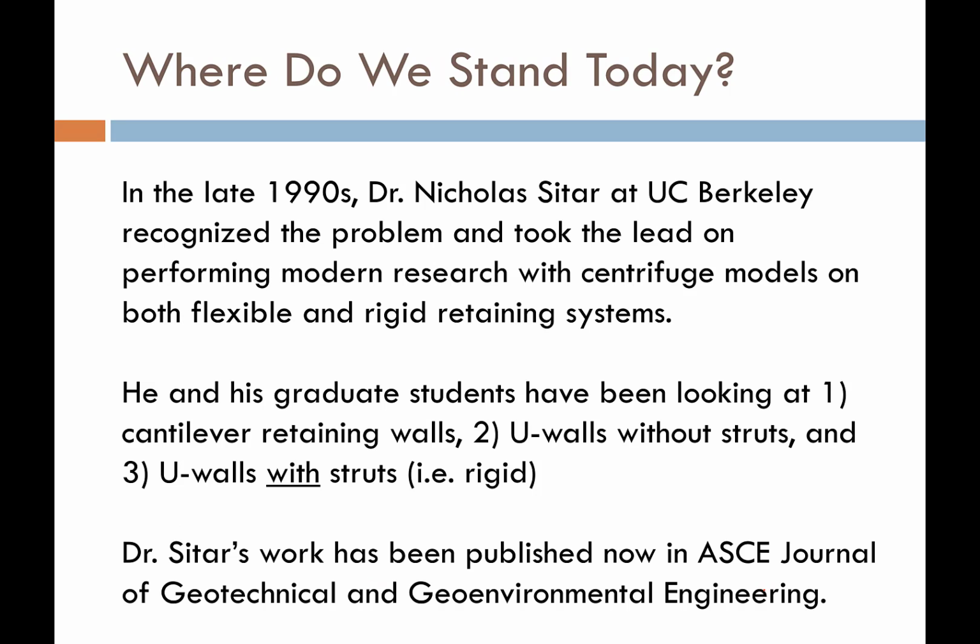But in the late 1990s, a great researcher who's a friend of mine, Dr. Nick Sitar at University of California at Berkeley, decided to tackle this problem. And he took the lead in performing a lot of modern research in scaled physical models within a centrifuge, where he would instrument these models of these walls and spin them, and then apply an earthquake motion in these models and measure the force in the models and then scale them up to the prototype scale.